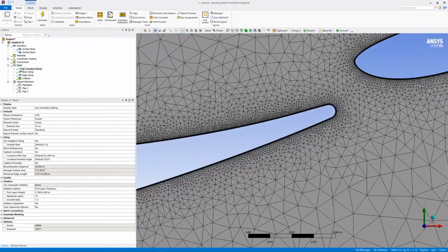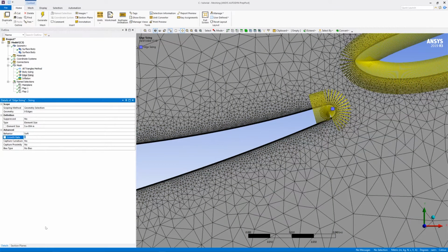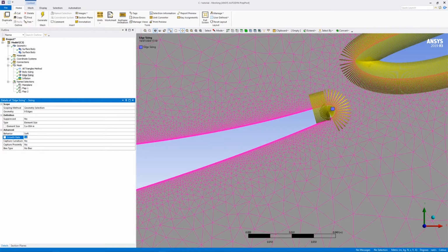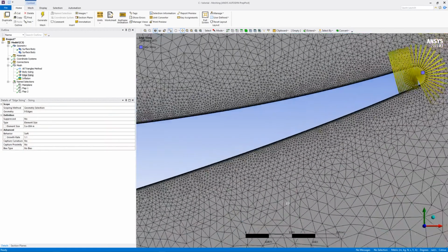So what I'm going to do is, on this edge size, change the growth rate to 1.2. Sorry, 1.1. Just to slow the growth of the mesh elements away from the aerofoil, give us a greater area of refinement. It's a bit better.